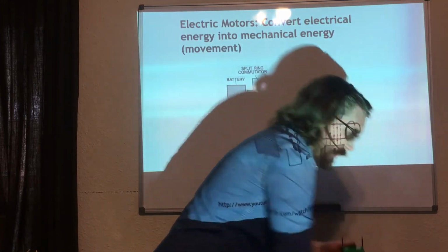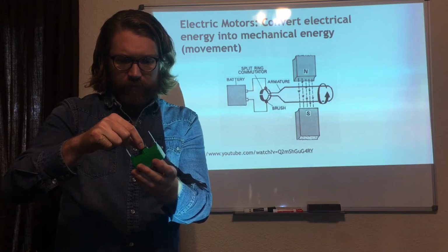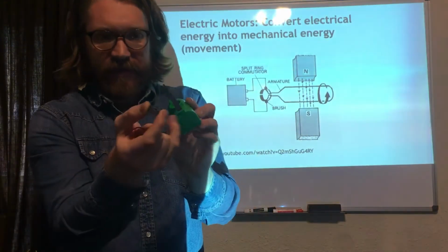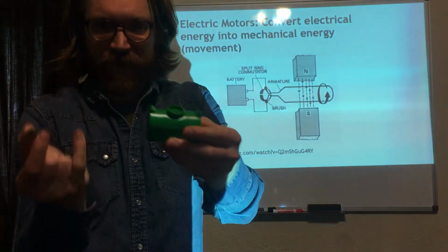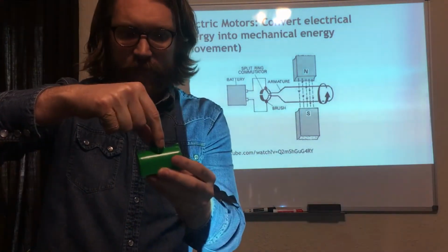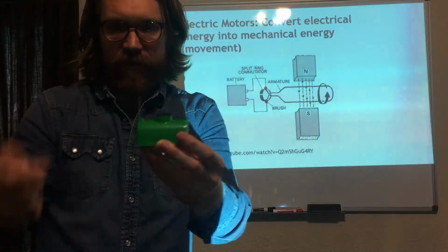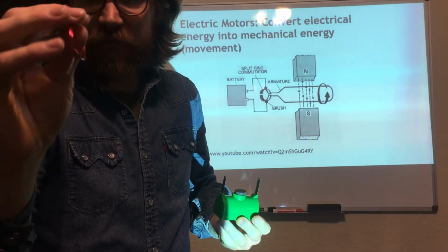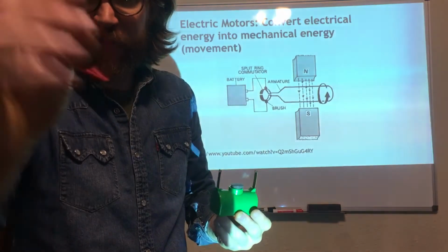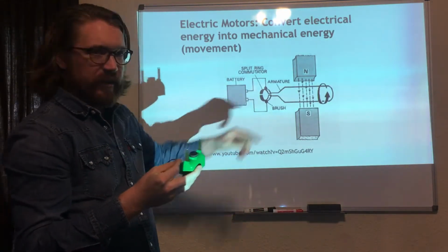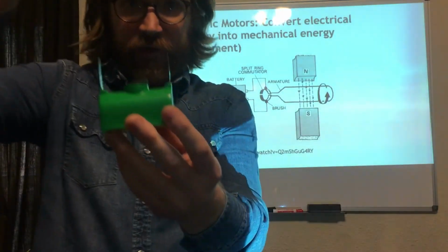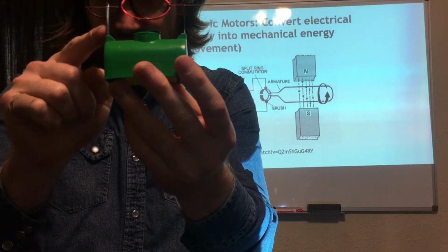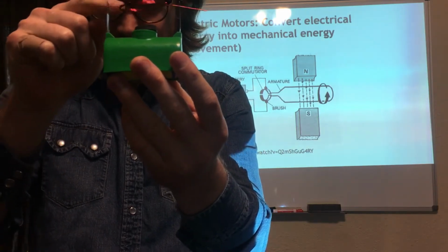I have tried to build one, and here's what I have. Okay, here I have a D-cell battery, okay, that is connected, the ends are connected to these metal poles right here. I have a magnet, it's actually 2 magnets that I'm putting on the top right there, and I have a piece of copper wire that I've shaved off one side of both of these arms, just like that right there. So when I put the copper wire onto this, okay, I create a full circuit, and as you can see, the wire starts to move.